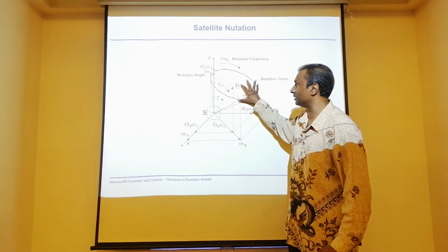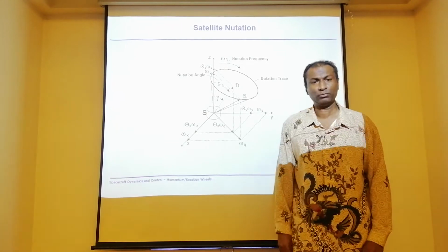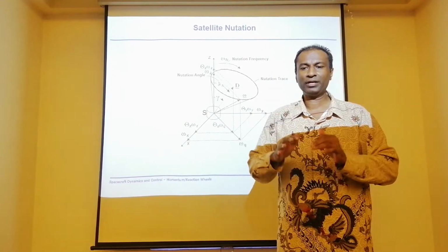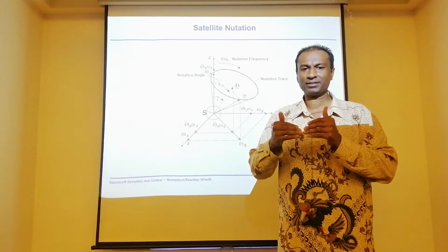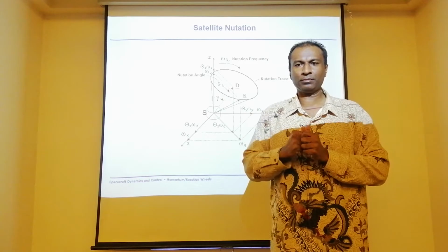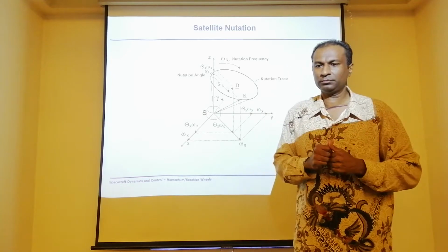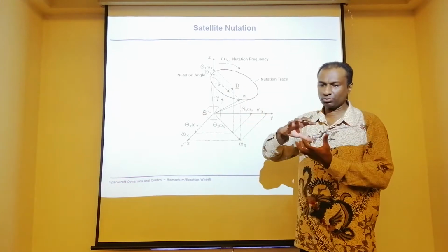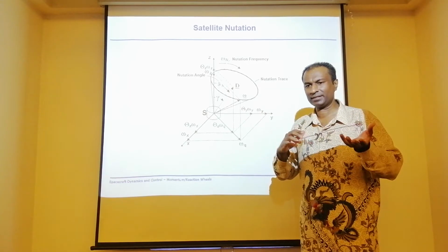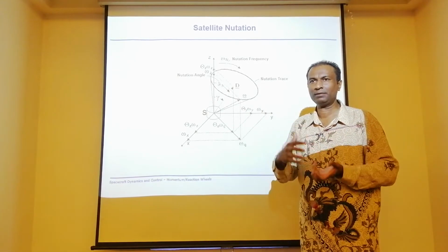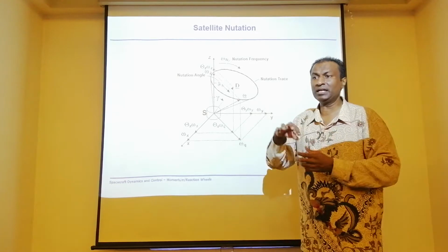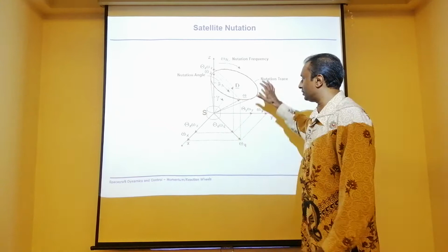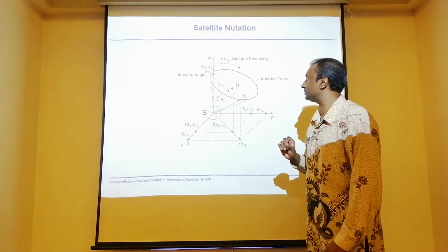Technically, nutation does not always happen. It will happen more often than not just after the launcher injects the satellite into orbit. You'll start tumbling. So nutation is the tumbling mode. That's why, if you learn satellite technology, we also mention the tumbling mode. Tumbling mode is when a satellite tumbles, and tumbling can also incorporate the nutation motion. Now, this can be counter-reacted.